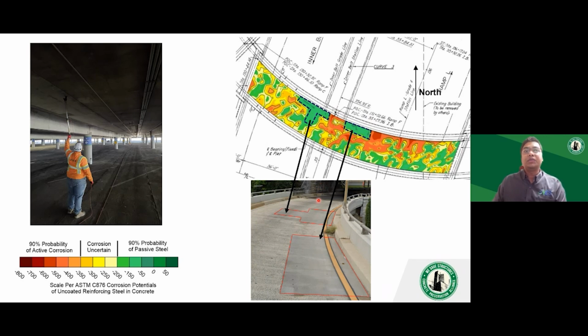In these two areas where the steel is passive, the steel is exposed to good quality concrete without any chlorides. These are chloride-free patch repairs. Whereas as soon as you move out of these patch repair areas, you have chloride-contaminated concrete, which is still causing the steel corrosion. And that is easily reflected in the corrosion potential survey. Very powerful tool. It can tell you what percent of the area is actively corroding and how widespread your corrosion is throughout the structure.